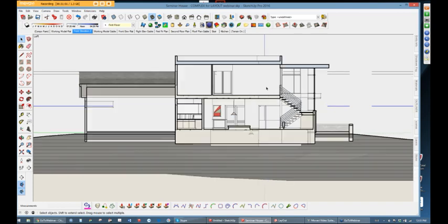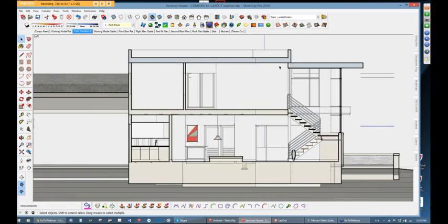But what I want you to notice here, see all these areas in SketchUp that are just kind of blank, sort of odd lines and things showing up in there. These are recessed lights in the ceiling. That's stuff in your SketchUp model you're probably not going to be able to get rid of, but in layout you can cover this over, essentially poche all of this stuff.